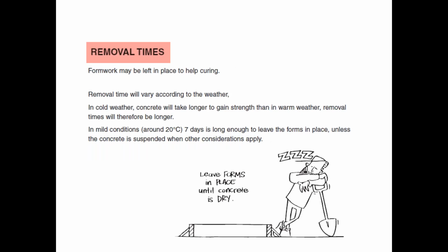Now, you remember we talked about curing and keeping it wet for as long as possible, the 3 to 7 days, etc. Well, if you've got formwork in place, you need to leave it there for a few days afterwards to stop the excess water coming out. So you need to hold it in place to keep the concrete damp so it gets its strength and cures well. If you leave the formwork in place, that helps with that a lot more. Any excess water will just come out the top.